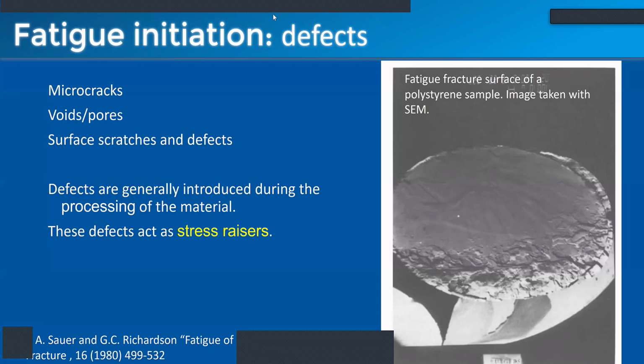Okay, moving on to the next slide, where I've got the term endurance limit highlighted in yellow text there. So this is another term that's associated with fatigue testing. Some materials may have what's called an endurance limit, where they are able to withstand repeated loading and unloading of cycles to infinity. In theory, you could unload and load that sample infinity times and it would not fail. In practice, obviously, eventually the material would fail due to entropy, but you reach the end of your fatigue testing, the maximum number of cycles that you want to test, and the material does not fail. The applied stress that is associated with that point of non-failure of the device is called the endurance limit.